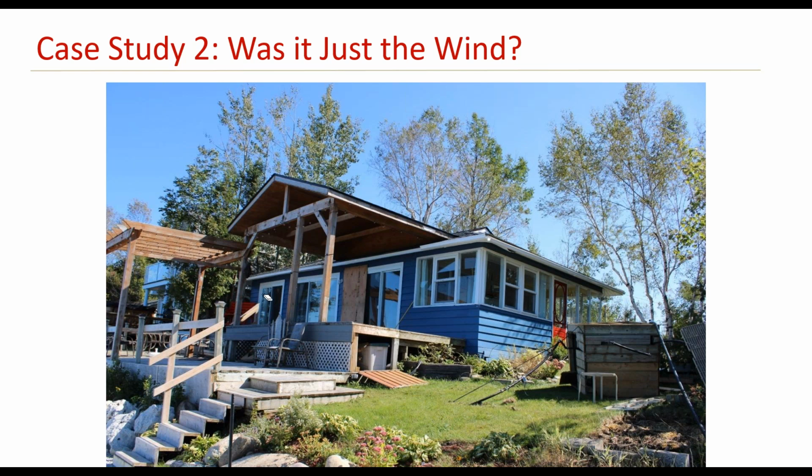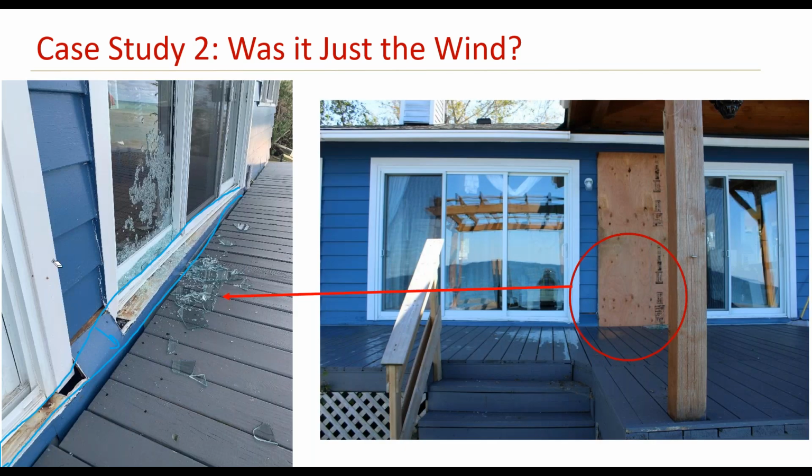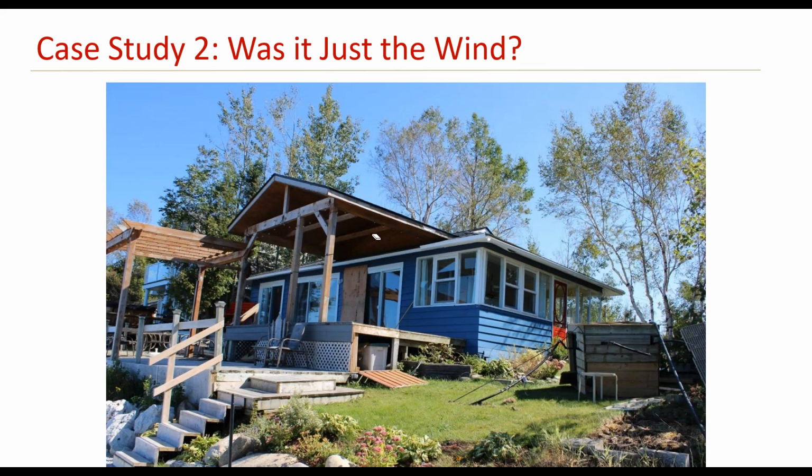Well, this type of failure, I wouldn't say any additional load on the roof would cause it, because this was a pushover kind of failure where it was pushed this way. Of course, that's not to be taken generally, it's case specific. But in general, in an engineering sense, if this was getting pushed this way and you have a weight on top of it, that would stabilize it a little bit from being pushed, not make it worse. Of course, other factors would be taken into place, the height of the wall and stuff like that. But I wouldn't say that the weight would contribute to that failure. If any, it would have actually stabilized it.